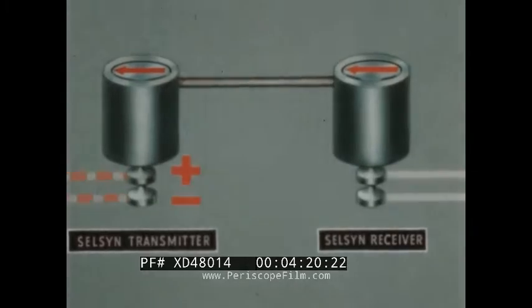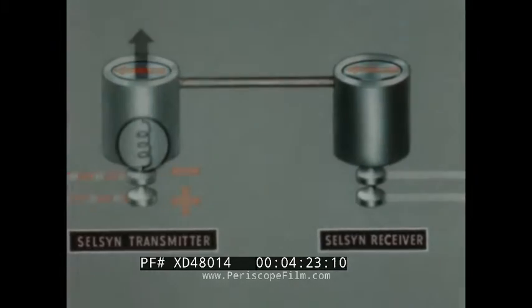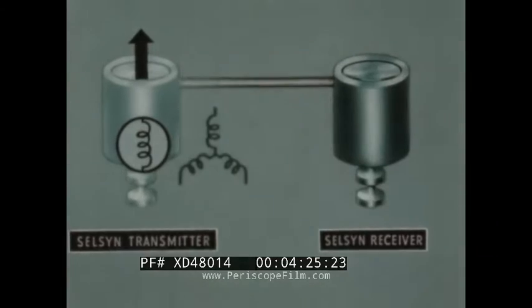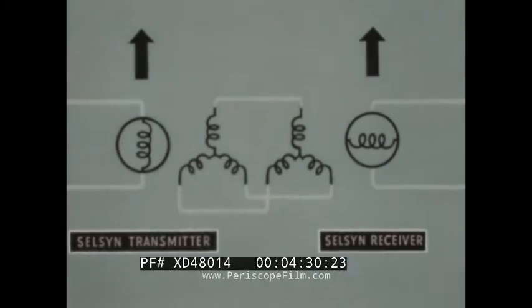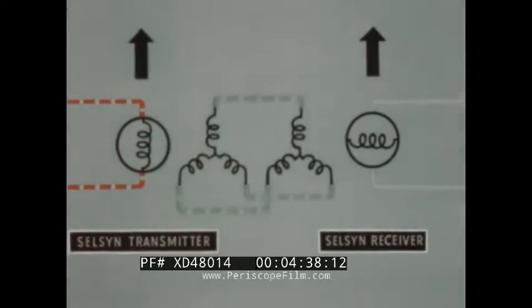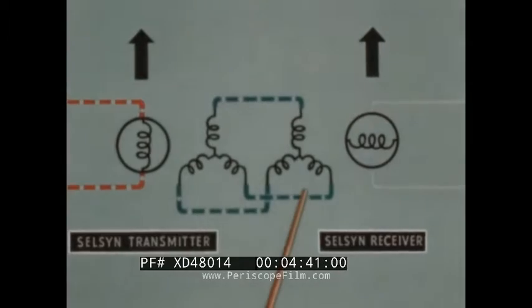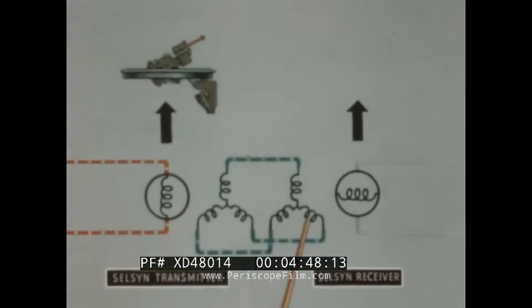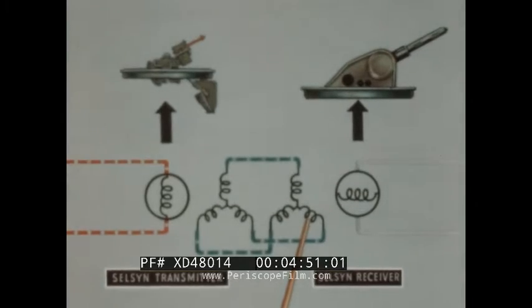Selsyn units are represented as a single winding or rotor, which can be turned, and a triple winding or stator, which is stationary. The AC supply to the transmitter rotor induces voltages into the stator, which are carried through wires to the stator of the receiver on the turret. These voltages represent the sight position. When sight and guns are aligned, no voltage is induced from the receiver stator into the receiver rotor.